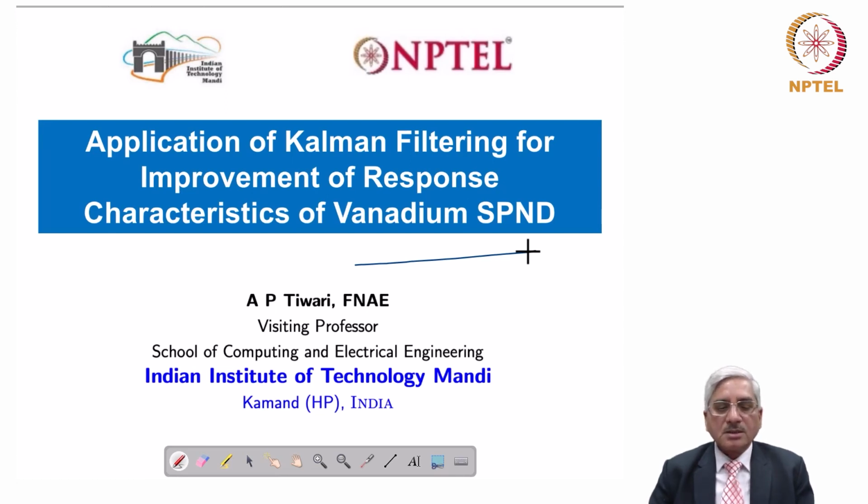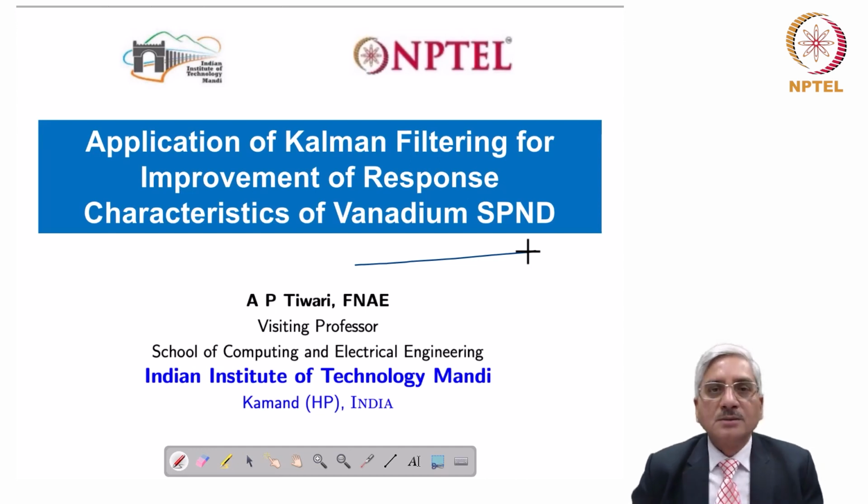So essentially we are going to attempt the design of Kalman filter and its selection of its parameters so as to get a good design with the intent to improve the response characteristics of a vanadium self-powered neutron detector.